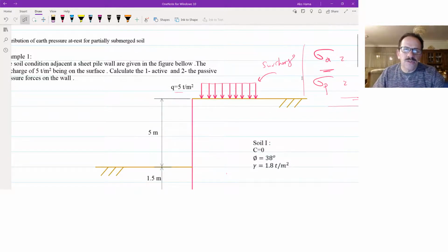That means it could be a 3-story or 3-floor building, because for residential or house buildings, we can say about 1.2 ton per meter square for one floor, so this can be a 4-floor residential building.